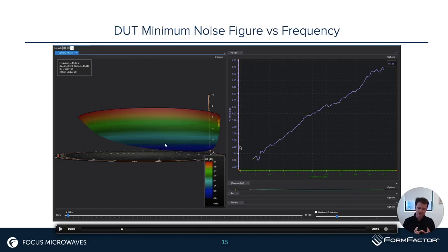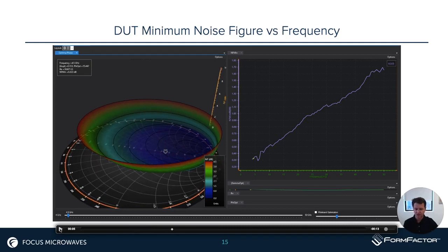so the phase shift should follow the trend of gamma opt. That's going to start increasing and going to the west side of the Smith chart. So let's just click on that. So now let's take a quick view. We can see the optimum point is here, and as we increase in frequency, this optimum point should be shifting in this area. Not only shifting in this area, but it should also increase. So let's get a visual of that.